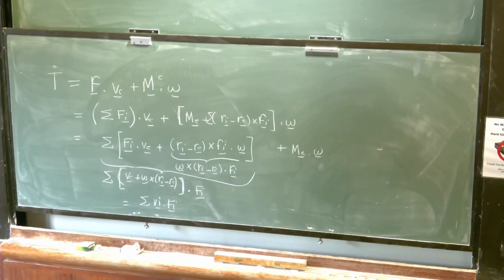We did this problem before. 2 wheels, shown again here, represent 2 extreme conditions of mass distribution. For case A, the mass m is assumed to be concentrated at the center of the hoop in the axial bar of negligible diameter. For case B, the mass m is assumed to be concentrated at the rim. Determine the speed of the center of each hoop after it has traveled the distance x down the incline from rest. The hoop rolls without slipping.